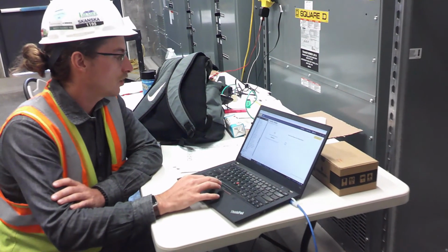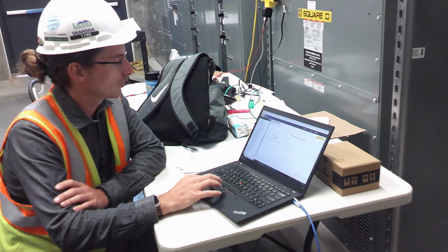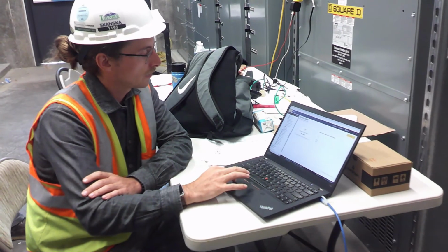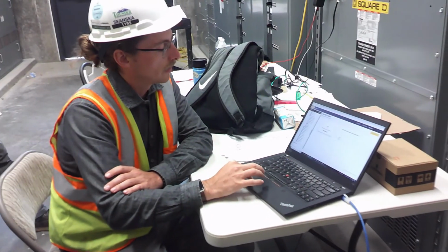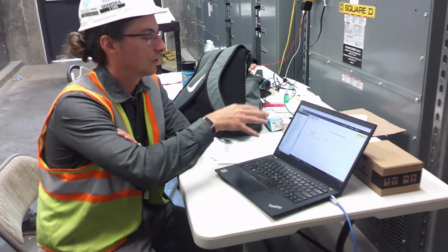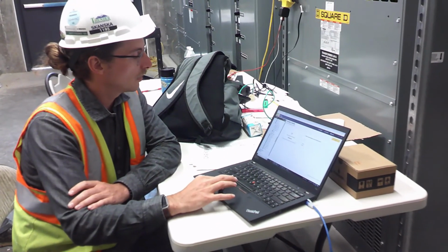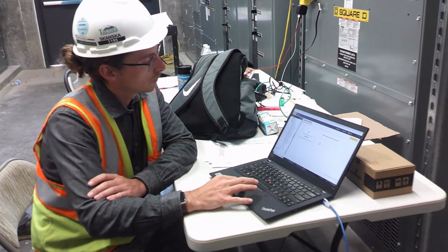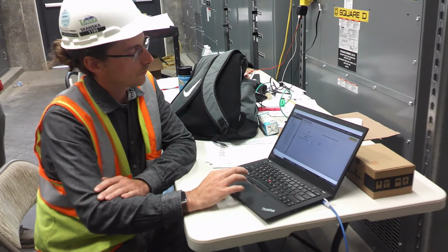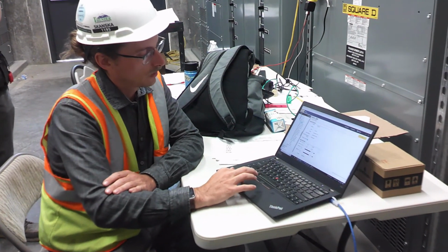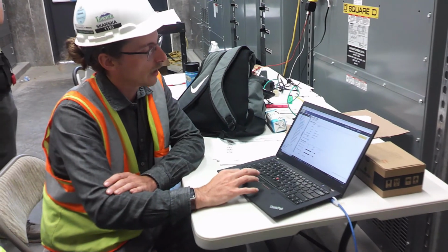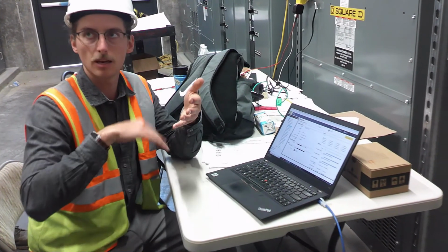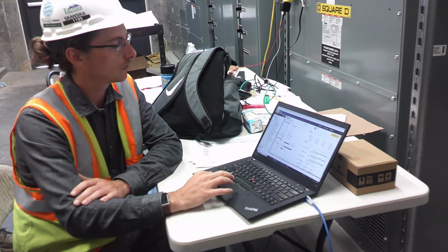Once you expand the zone, I'll just do this classroom for example, that'll show you all the bridges, which is the device that has the actual drop down, and then the relays and the panels that have been loaded into that zone. You can go into the bridge, and you'll see all the controllers. You'll get the container for the controller, which just shows you the overrides, and below that you'll see the actual dimmers and relay outputs that have all the settings, which are the same thing that you'll see on the app, just laid out a little differently.